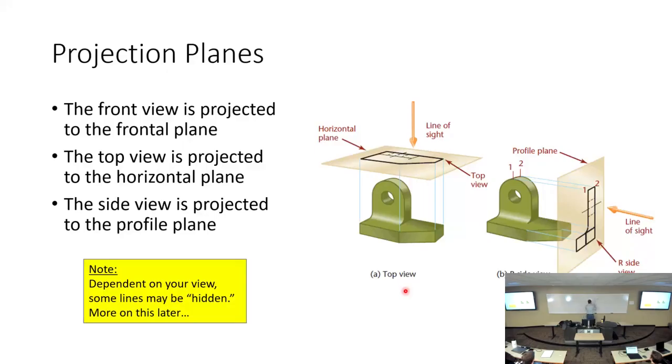And so if I was looking at, let's say, the top view, it might look like this, right? And then the side view might look like that. And notice I'm using a very specific legend. Notice how the line I drew through the center of the hole looked like that. I didn't choose that arbitrarily. That's typically what we do in engineering drawings. Notice how the hidden lines I drew as a dashed line. I didn't choose that arbitrarily. That's typically what we do.